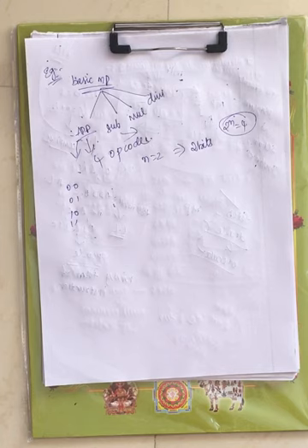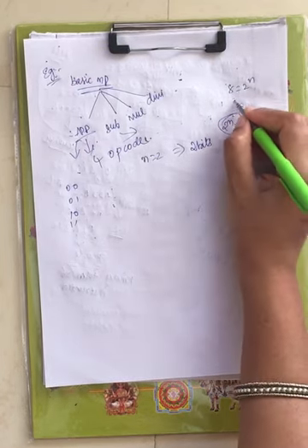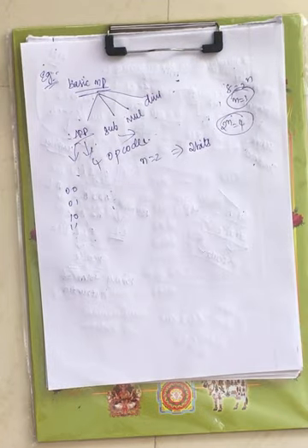Now consider a processor that has 8 instructions. Since it has 8 instructions, each instruction has to be converted to binary form, the low level language, so you will have 8 opcodes. Now the opcodes will be of how many bits? You have 8 instructions, 2 power n, and n equals 3. So the opcode will be of 3 bits. The different possibilities with 3 bits are 000, 001, 010, 011, and so on up to 111. That is how you have to identify it.